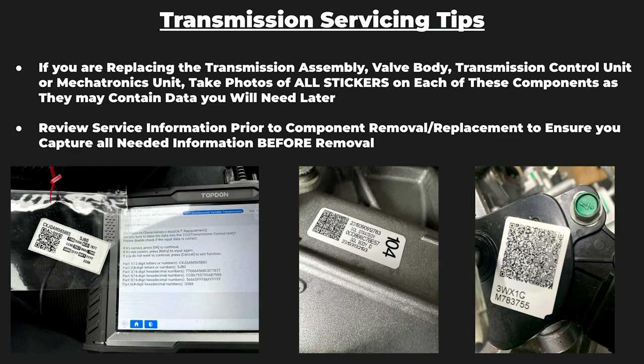So again, just a simple tip when we're doing any transmission service, make sure you are taking pictures of every sticker you see before you proceed any further with transmission service. So just another tip here that's really important to keep in mind.